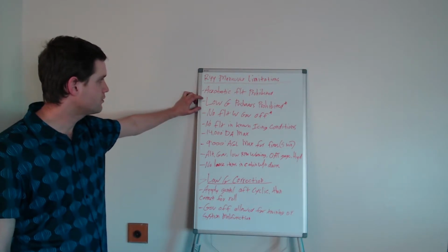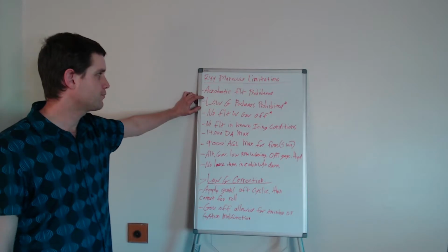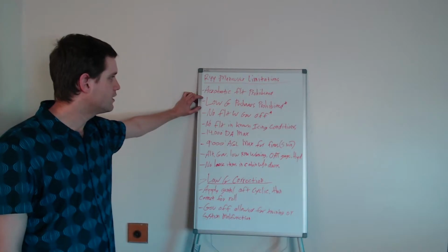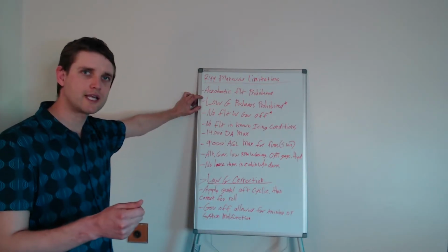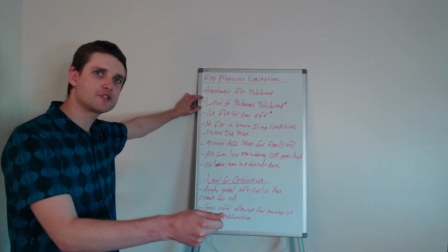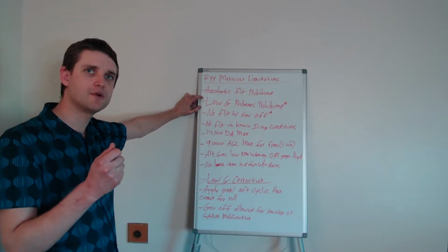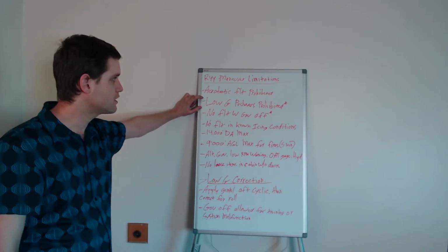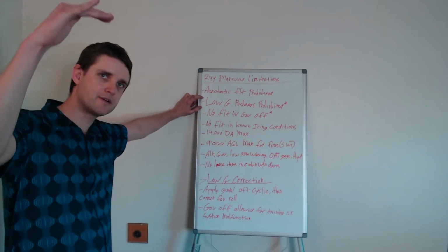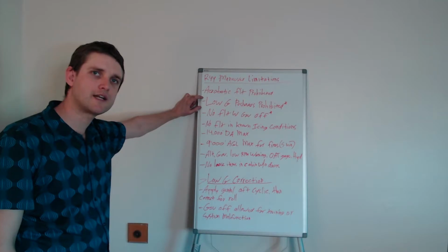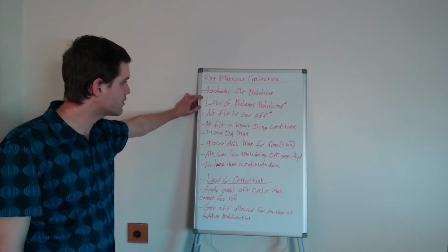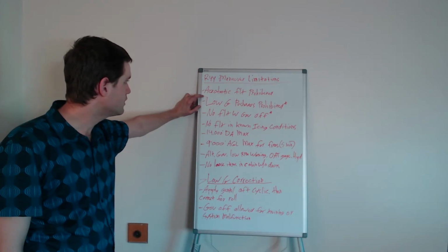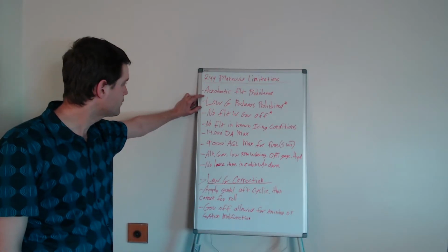So number 2, we have low G pushovers prohibited. As I explained in the SFAR 73 awareness training, which is the previous lesson I did, a low G pushover is essentially where you're flying in level flight and you suddenly push the cyclic forward, or you go from a climb and push the cyclic forward. The result in either one of those cases is that the fuselage of the helicopter is no longer free hanging from the rotor system, and you can actually cause a jackknife situation between the inside of the rotor hub and the rotor mast, which can basically end up in catastrophic failure of the rotor mast.